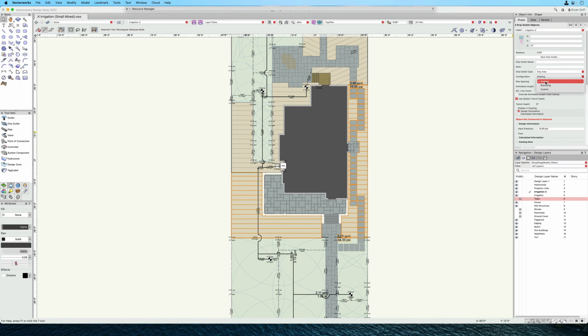You'll notice that if I choose branching, it changes. I have an estimated full length of pipe, but my average length, based on the direction that I have the line going, allows me to model this up appropriately and understand that I only have 12 feet average worth of friction. Okay, but I have 487 feet of pipe total here.